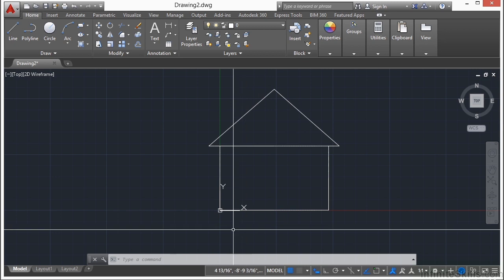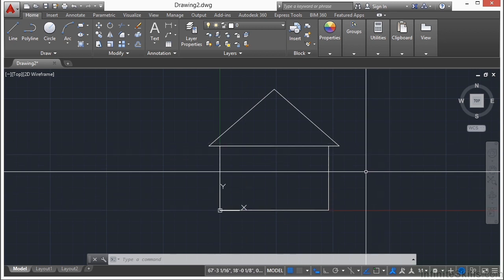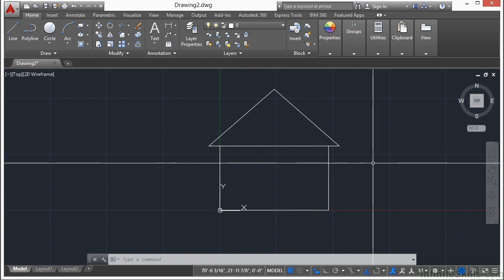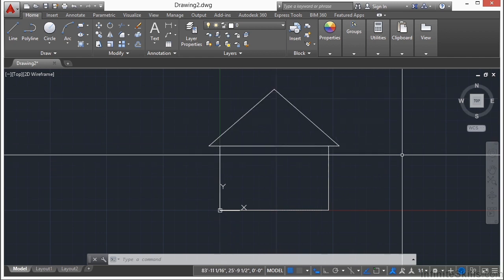We did some absolute coordinates, absolute lengths. We used the ortho command to help us lock it in vertically and horizontally. We also used some relative polar coordinates, so we can draw in that way as well. And before we go, I want to review drawing with coordinates.